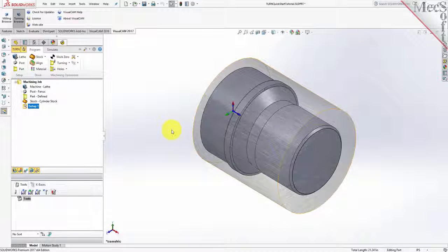They follow the convention that the spindle axis of rotation is designated as the Z-axis. Secondly, the axis perpendicular to this axis, along which the tool travels to cut into the stock, is designated as the X-axis. So the part and spindle rotate about the Z-axis, and moving a tool along the Z-axis provides the direction of feed, and moving it along the X-axis provides the depth of cut.